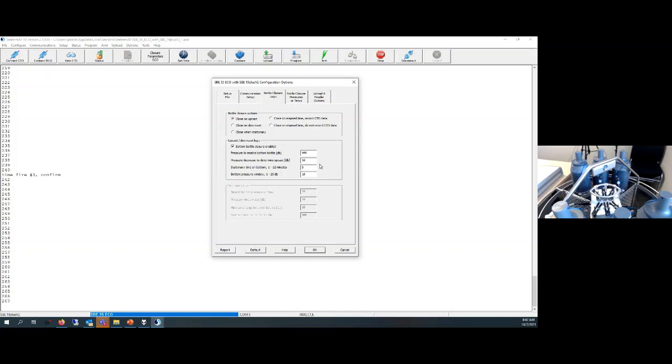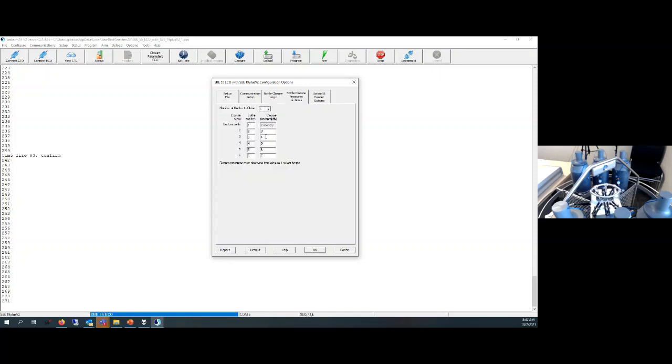From there, we'll start the upcast. It'll rise by at least 10 decibars, and we can tell it to close bottles at, say, 400 meters, 300 meters, 250 meters, 100 meters, and 10 meters. At that point, it's going to close bottles at these points.